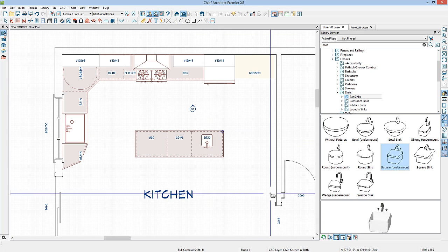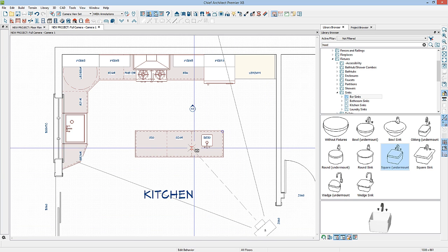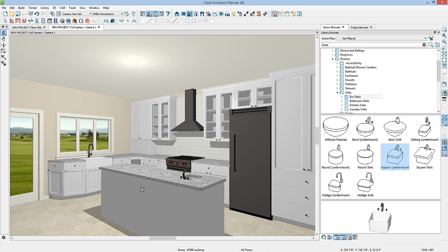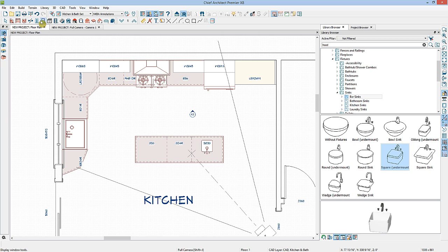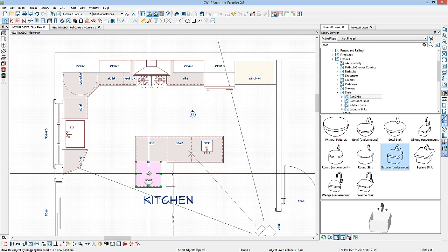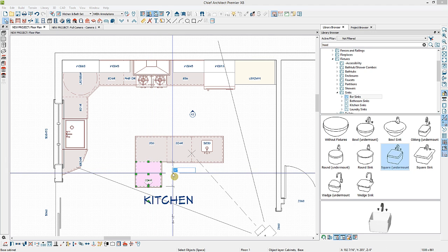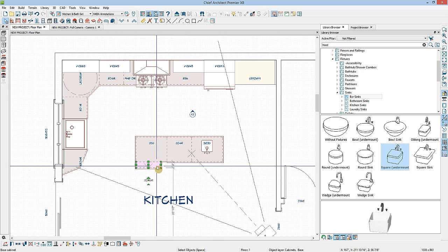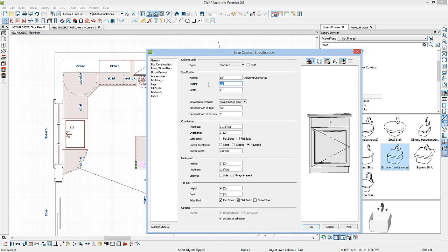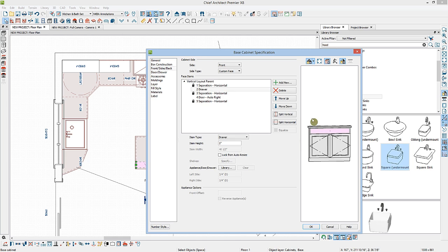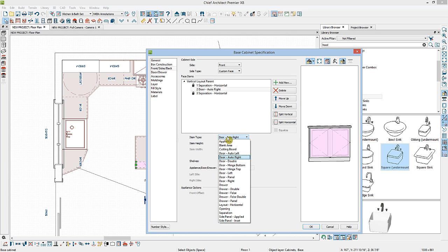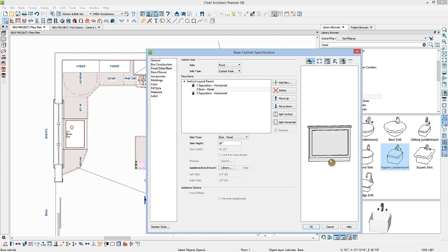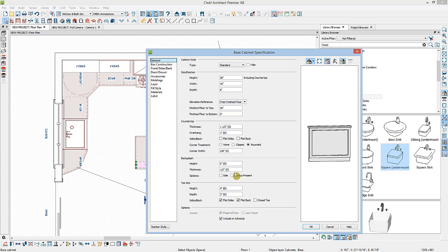And then we'll take a camera view of this from the back of the cabinet. And what I want on the back side here is two panels. So in the floor plan view, I'm going to use my cabinet tool again, my base cabinet, place a cabinet right up against the back side of this one, and here I'm going to make this cabinet 6 inches deep only, and then double click on it. And I'm going to make the width 42 inches wide, and I'm going to delete the drawer and simply place a door panel here. And I'm going to remove the toe kick altogether. So we'll go to the general panel, and here for the toe kick I'll just make this as 0 and click OK.